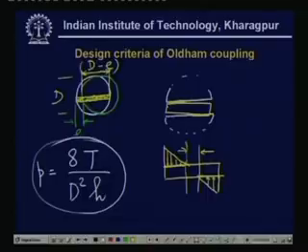But this bending stress is again fluctuating, so it leads to fatigue stress, that is the variable loading, and the shaft may be subjected to high fluctuating stress, which may lead to failure. So it's always advisable to reduce the weight of this floating member, because then the bending stress will be small. Another defect is that there is always rubbing taking place here.